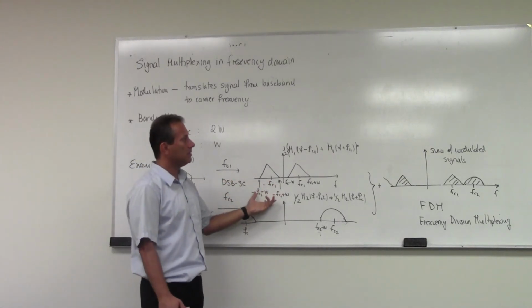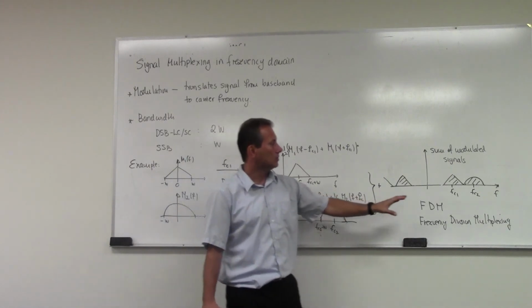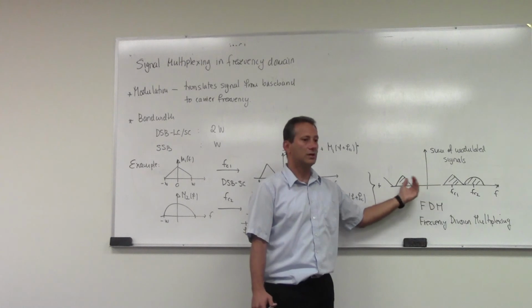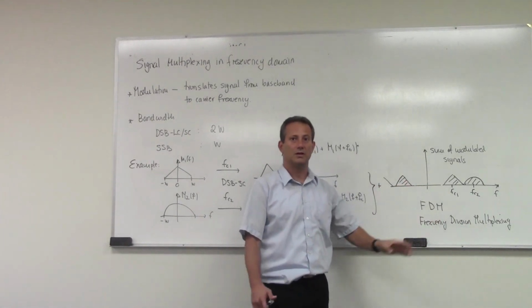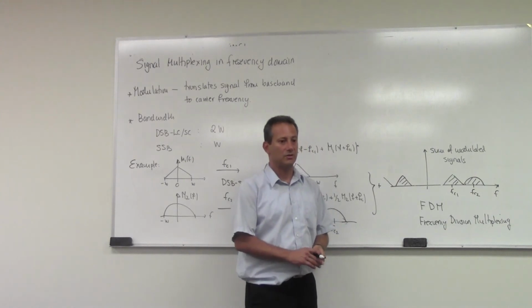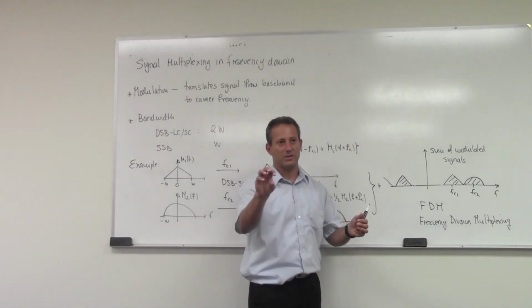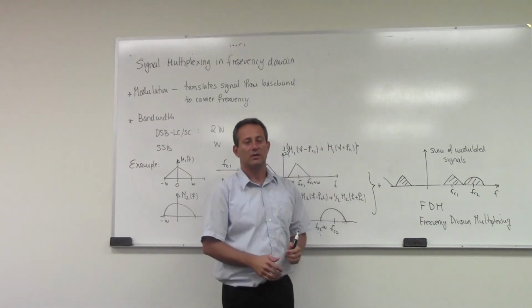And as I said, the main purpose here is to use the same transmission medium to send multiple signals. And then when you demodulate through the process of filtering, you're actually going to eliminate all the other ones but the one that you care about. And what you're doing on old dials is exactly that. You're actually selecting the station. You're moving the filter to the station that you desire.